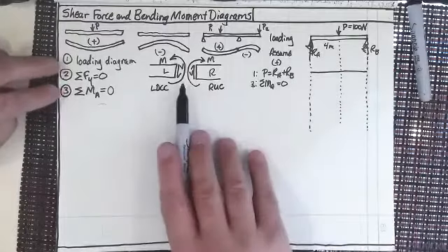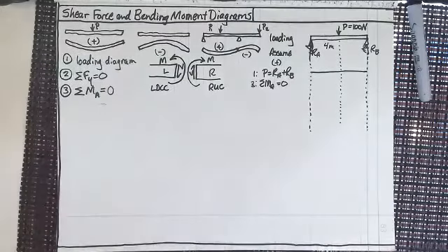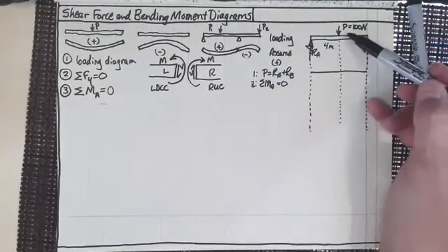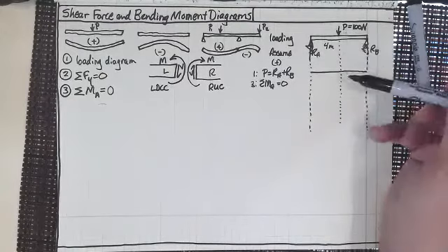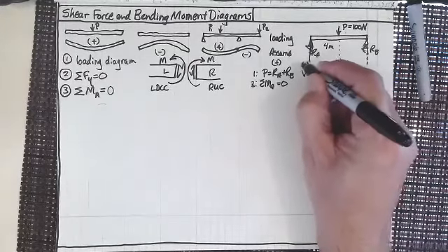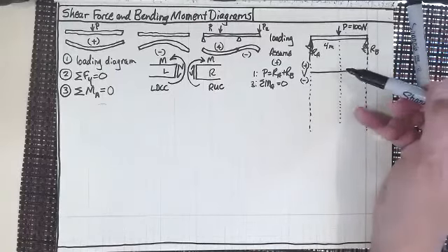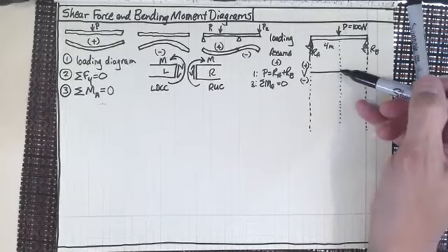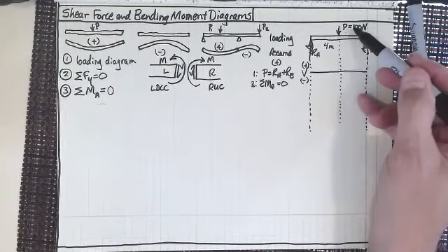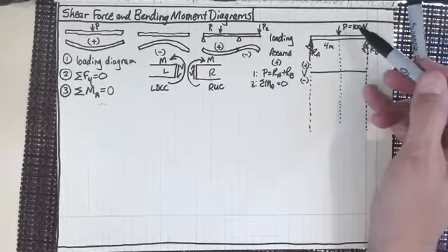Just like I did in the last lecture. And I wanted to show you this in the last lecture because now we're going to extend beyond that. We're going to realize that the loading diagram is the derivative of the shear force diagram, right? The loading diagram is the derivative of the shear force diagram. Or we could say that the shear force diagram is the integration of the loading diagram.